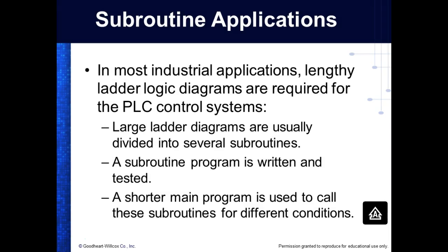And in most industrial applications, linked ladder logic diagrams are required for the PLC. Like I said, we're doing very small programs, but you got to understand, you get out here and you get a PLC that's running a sure enough production line. There's not going to be any nine-line programs, right? Unless it's a subroutine. So what we need to do is we need to be able to understand we can take that large ladder diagram and divide it into several modules or subroutines. Now all of a sudden it makes it a lot easier to manage that program. I mean, a lot easier.